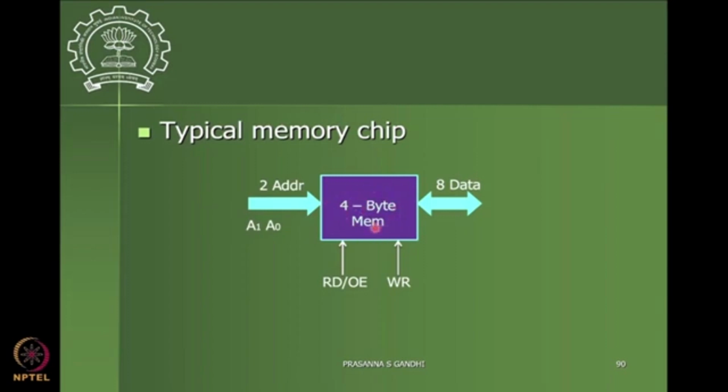Like that, if you have larger and larger memory size, you can see how long the data bus that you need. Or if you have, say, 8 lines of the address bus, then what is the maximum number of registers that can be there in the memory? 8 lines means you can have 256 registers in that memory.